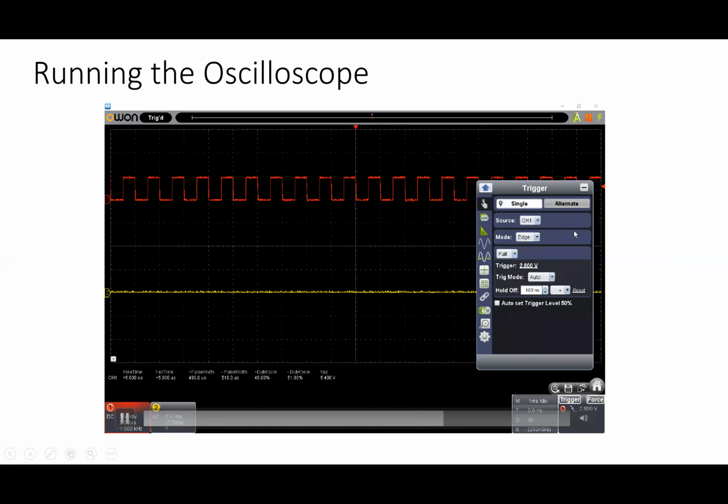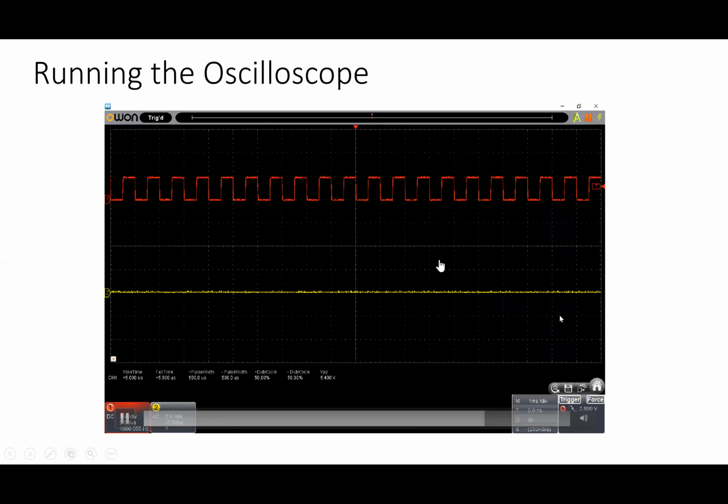All right. Oh, you notice, by the way, that there is a hold off. This is for doing this delayed triggering that I mentioned to you. So if you were sending a trigger pulse into that multi-purpose pin, which can be programmed from the settings, by the way, on this home panel, then you could look before even the trigger event.